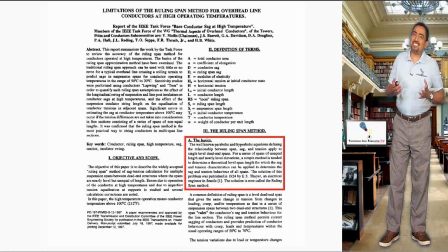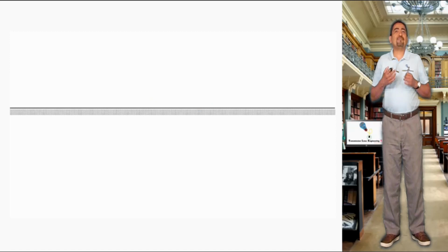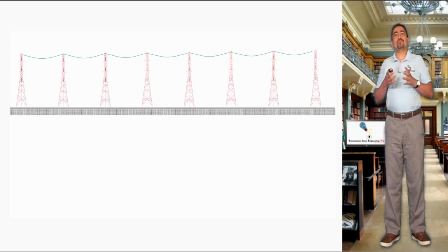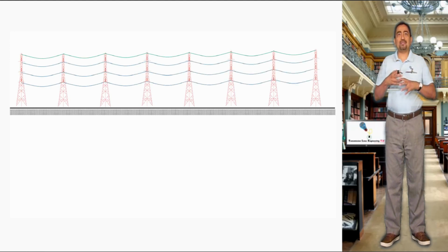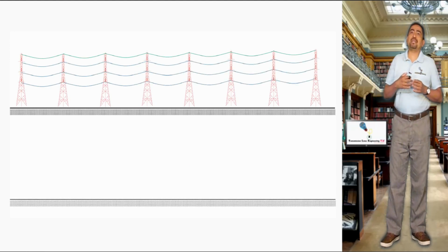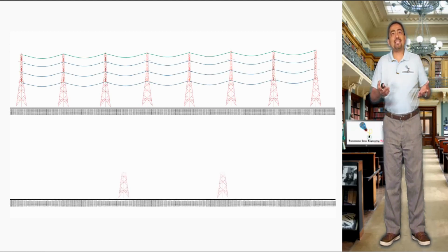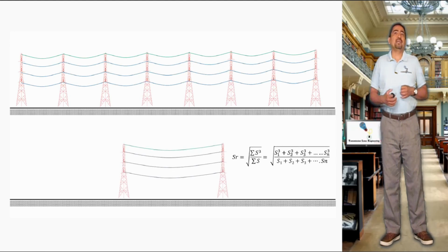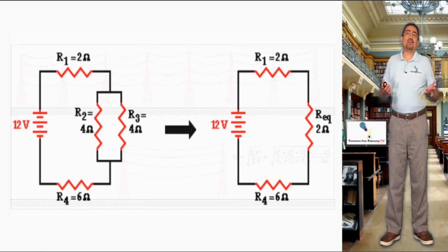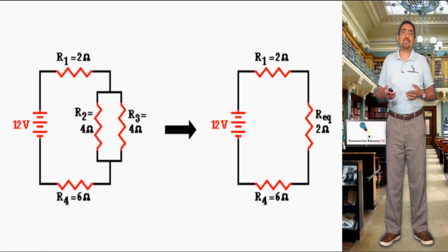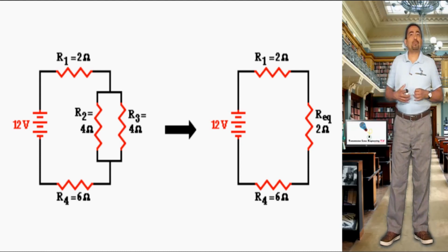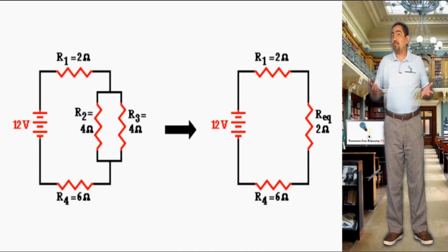This method is based on the fact that a multi-span line can be reduced to its equivalent span, whose sag calculation and tensions will be valid for each span that makes up the cable string tension. It is equivalent to an electrical circuit composed of several resistors, which are reduced to an equivalent resistance to calculate voltage and ampacity.